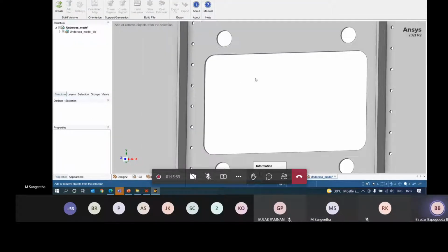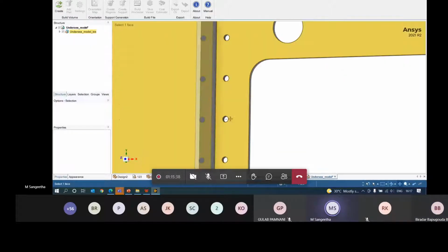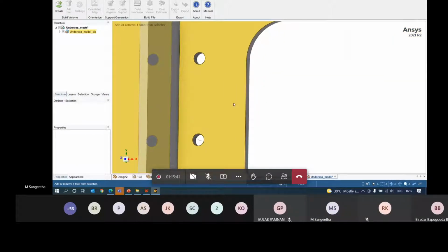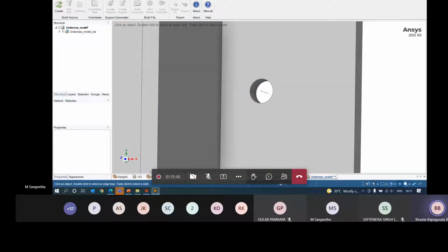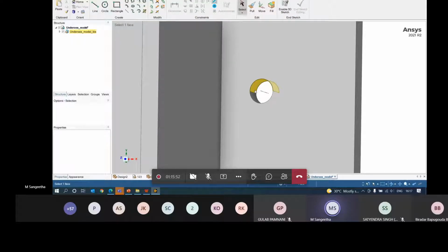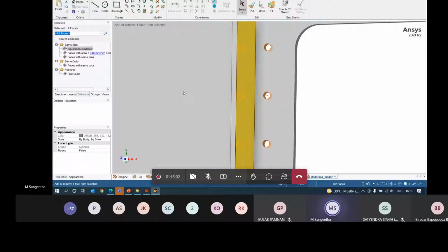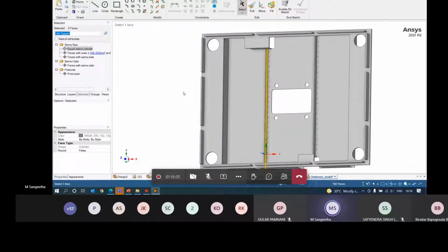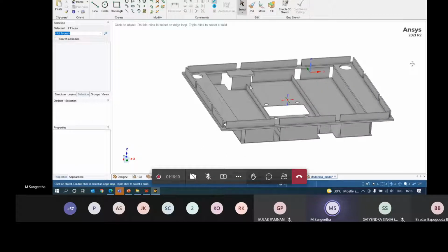Okay, so let's just directly convert it. Okay, so now I can go with the selection directly. Select these two surfaces, and go with selection criteria, equal radius cylinder, so that all the cylinders are selected here. You can see here, right? So all these are selected. Click on delete. When you don't need all of this, you can remove them easily.